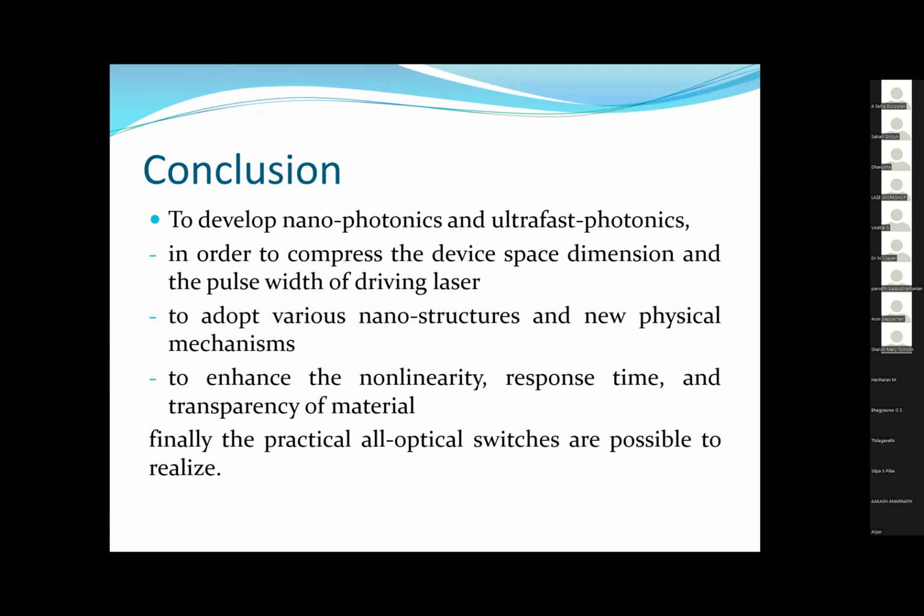On the foundation of developing nanophotonics and ultrafast photonics, to compress the device space dimension and the pulse width of my driving laser, I need to adopt various nanostructures and new physical mechanisms, and at the same time enhance the nonlinearity, the response time, and the transparency of the material. Finally, practical all optical switches are possible to be realized.